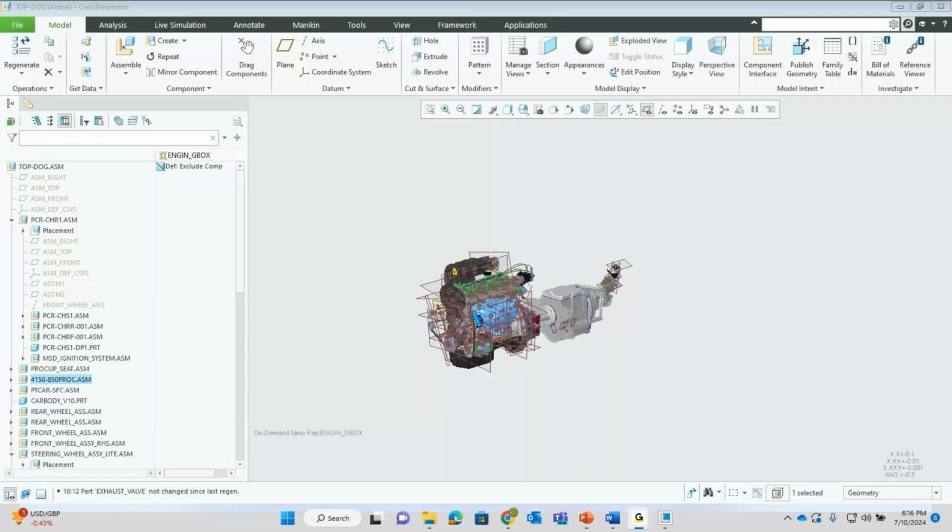I don't think it will open up the top level automatically. You will have to force it. You'll have to go on the external rep and say update rep. Then it's only going to look for the information that's in that specific rep, so it won't go to the top level assembly. In the instance that I had with just the gearbox and the engine, it's just going to look for those sub-assemblies or those components in that external rep.